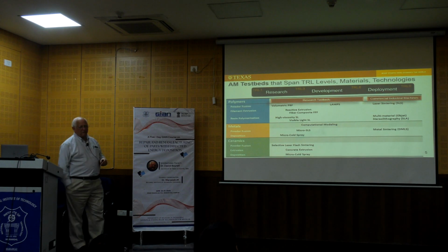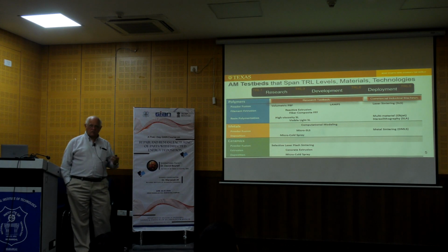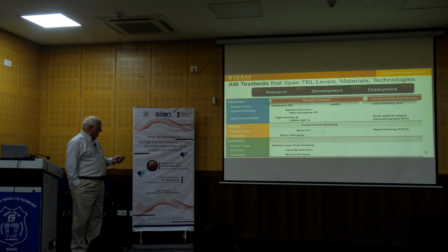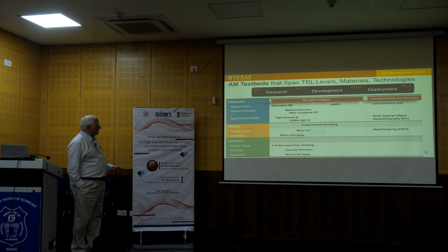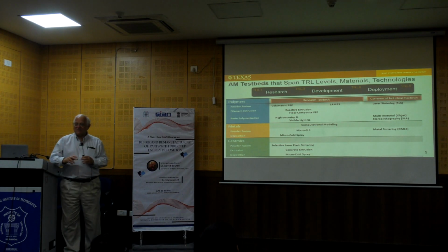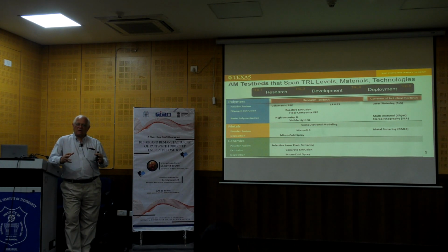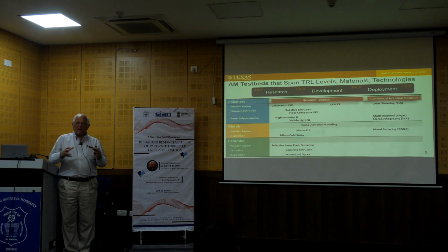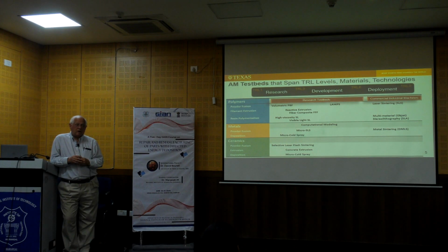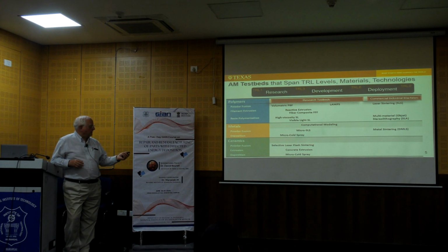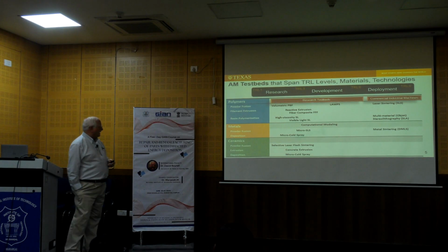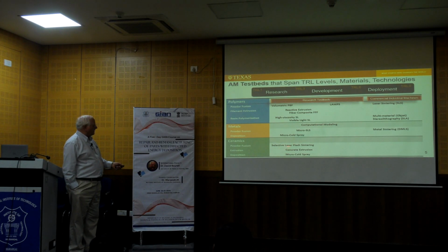In addition to the center's commercial machines, we have a number of research test beds for working with a variety of metals in various forms. Probably the most interesting is selective laser flash sintering, where we use laser sintering to loosely bind a ceramic part, then use flash sintering to very rapidly densify it. It's an exciting topic area. Dizzy Kovar and Joe Beaman at our place are working on that particular process.